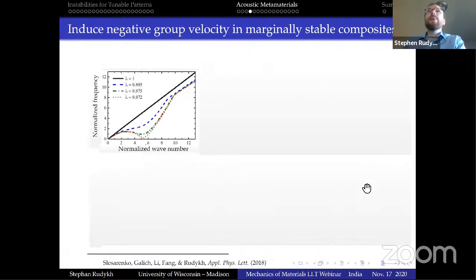Okay, so now one more example, where we're already starting to look into what happens when we approach instabilities. These are dispersion curves for the frequencies, again, against normalized wave number. We started from the more complicated things, and now we're going to simplify more and more to get to the bottom of things. So this is for a laminate, and this is the classical curve. We send a wave along the layers because there is basically no variation in properties in that direction. So there will be no band gap, and we also will have this sort of dispersion relationship.